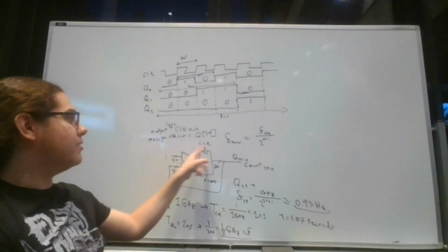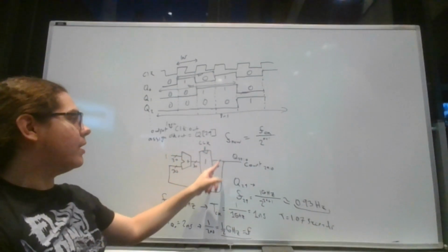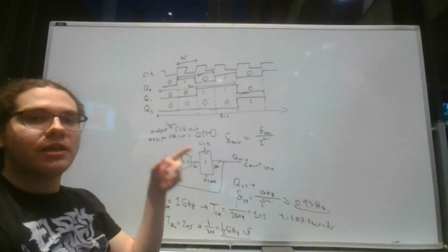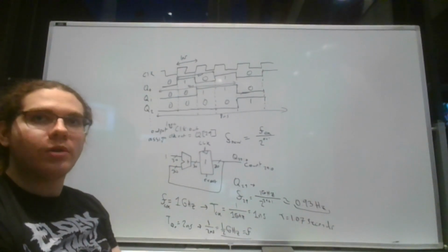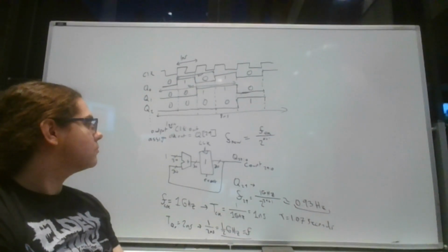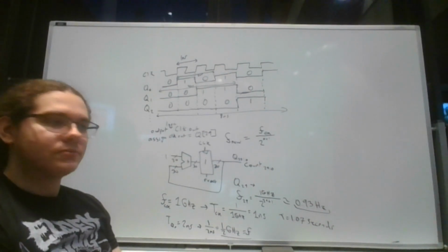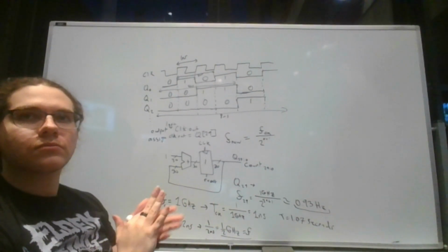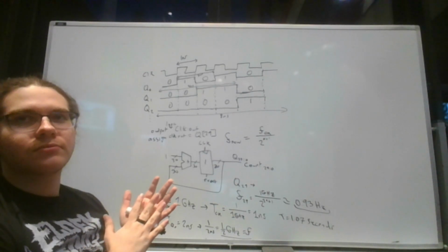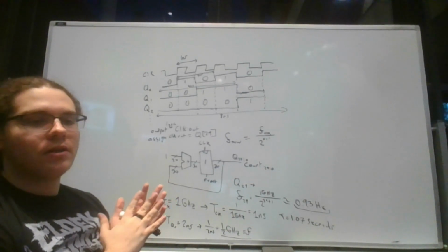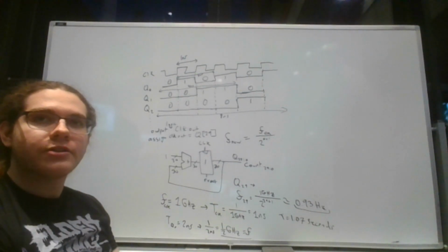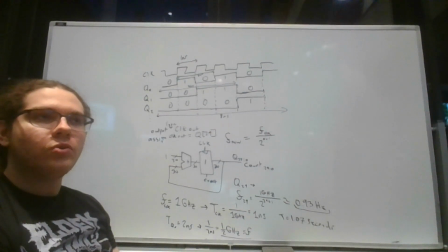Though more generally, this particular circuit is known as a counter. It's the counter. But in this particular application, since we're using it to generate a clock signal, we would then call it a clock divider. So it's both. I don't suppose you could do a clock multiplier, right? Because it's only dependent on how fast your clock goes, right? Can't make it go faster. Yeah. Not with digital, at least as far as I'm aware, not with digital logic. Analog stuff, you can do.